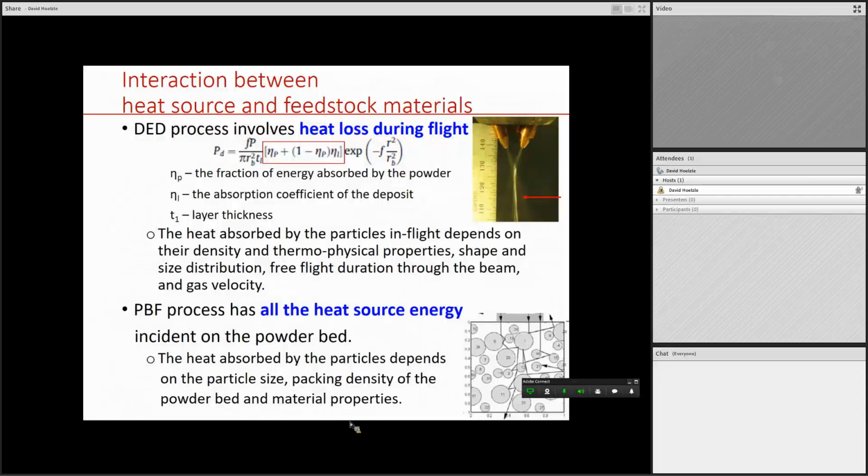And you can imagine, too, that a pretty significant amount of the light is actually reflected to the back end of the chamber. So it would essentially be energy lost in the chamber. So if you have a 100-watt laser, you're not getting 100 watts put into your powder bed. You're getting lots less of that.